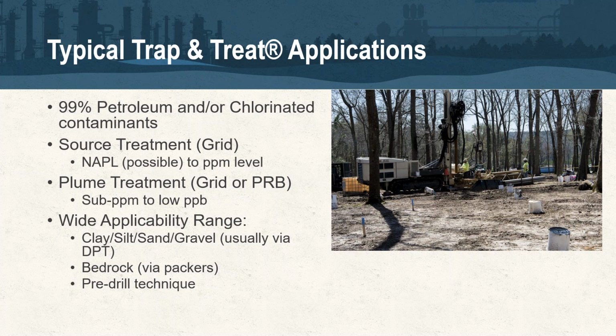And from a geology range, we also have a pretty wide applicability range dealing with your typical overburden lithologies: clay, silt, sands, gravels. What's going to change there is going to be your design, right? Maybe your injection spacing, your volume. All of those may change depending if you're in a sand site or a clay site, for example.